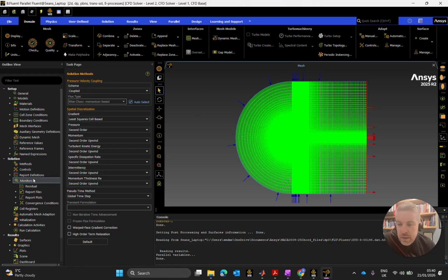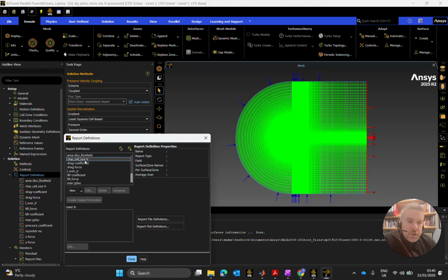I think our main difference is going to be made by the convergence criteria, that we are going to make sure that it is below our tolerance for a longer period of time, just to kind of, I suppose, mitigate the event where it dips down below and then it comes back up again, because it's just not fully resolved just yet. So yeah, that's what we're running with, and just want to make sure that our